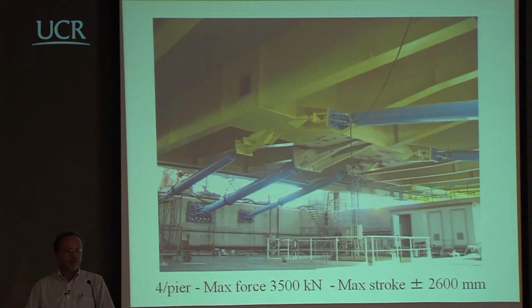They have a capacity of 2.6 meters displacement. And this one here is not a damper. This is a sacrificial element that is just keeping the deck in an unmoved position in standard condition. But when the earthquake comes, it breaks off, and the bridge starts reacting, controlled by the hydraulic devices.